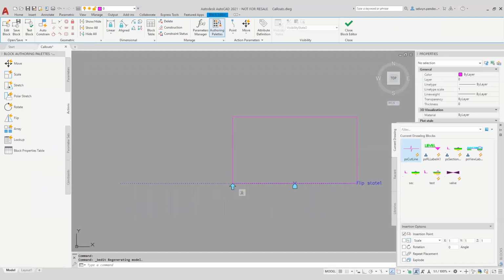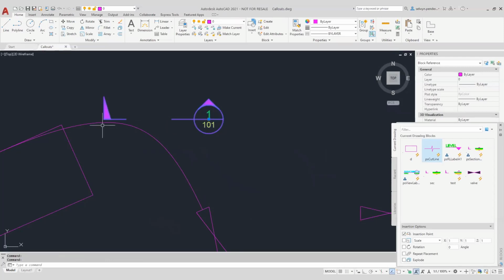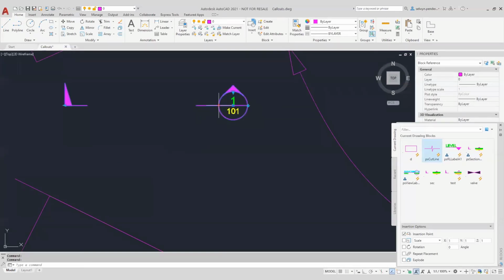But yeah, have a play around with parameters. If you go wrong, just undo, and just remember, continually test your block unless you're really familiar with the commands, because as you see with the call out that I did before, it's going to take me a while to sort out what the issue is with the one I've created with this parameter not appearing. It's something to do with visibility, but as we're limited with time, I don't have time to go through and work that one out, but you should have the basic ideas of what can be done with a dynamic block.